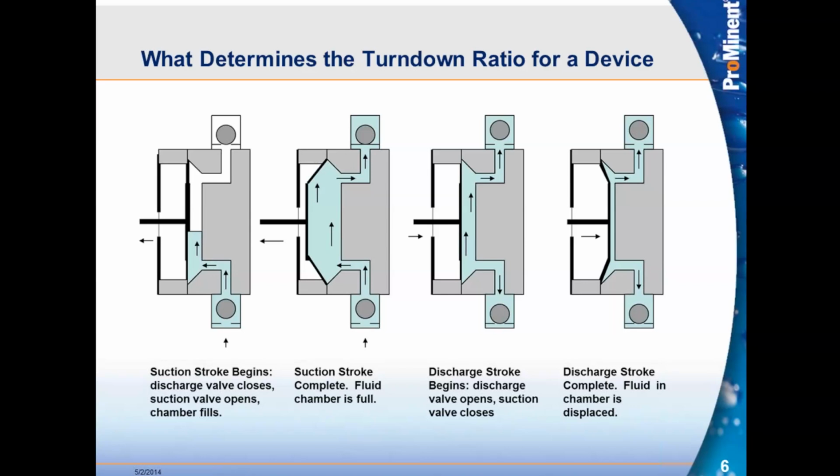Then we energize that diaphragm, either energizing the solenoid or the cam follower comes around or is pushed by the cam, and we displace that fluid, that volume that we pulled in, and it pushes the valve balls away from the center, pushes the suction at the bottom down into its seat. It's in check. Flow cannot go in that direction, so the pressure forces the valve ball at the top open, and we push the fluid out towards our process to complete that stroke.